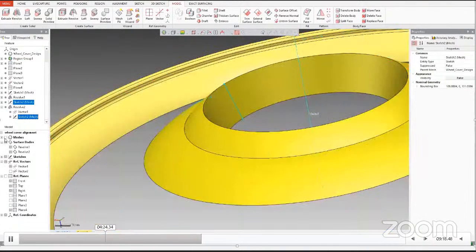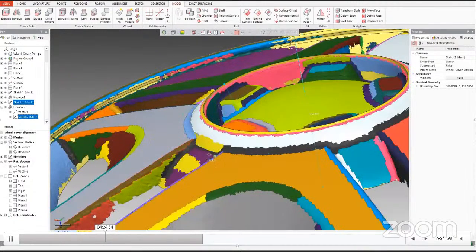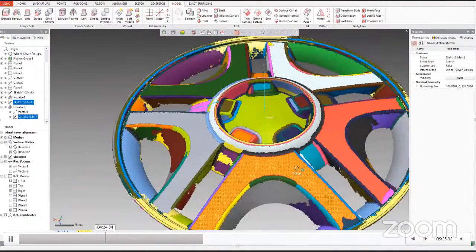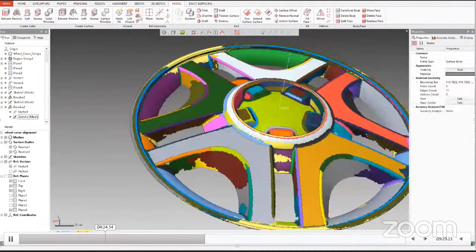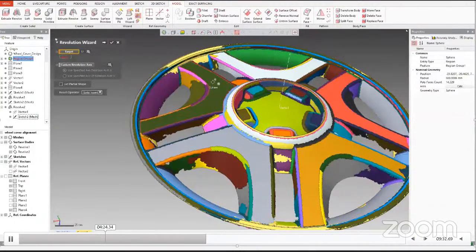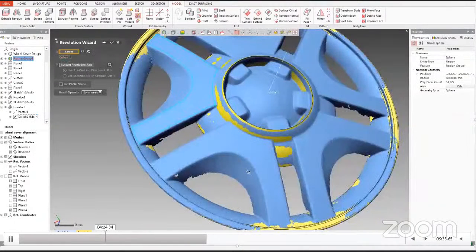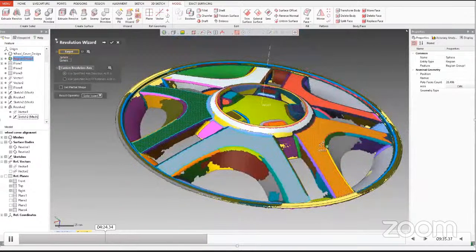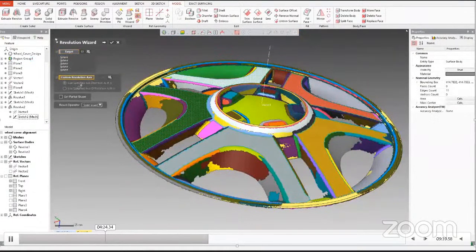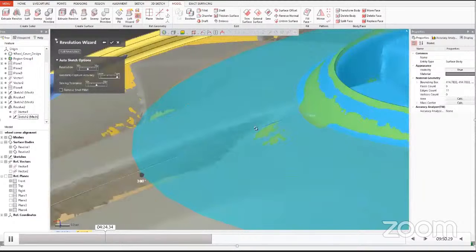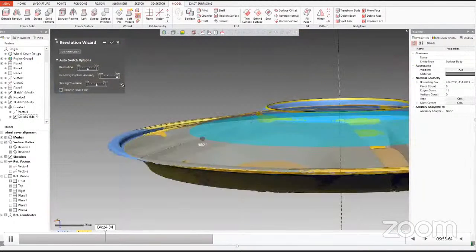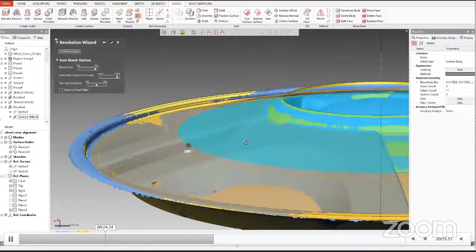So this inner sphere we have just created, circular profile. So let's create another circular feature, and for that we select these 5 ribs and also select the central axis and then select the surface insert and see the result. So once we are okay with the result, we can go for it.